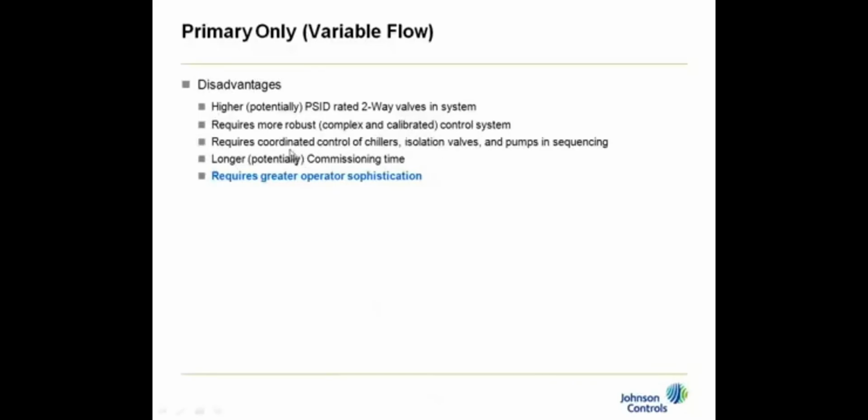Now, another disadvantage is that it requires a coordinated control of the chillers, isolation valves, pumps, which means that there needs to be a meeting during the design phase before everything is installed, with the consulting engineer, the chiller supplier, or at least the specified one, the pump supplier, the control supplier, and the valve supplier, to make sure everyone understands the sequence of operation that the consultant wants to use, and make sure everyone's limits are out there so that there isn't any problems with the system later. If that meeting is done ahead of time, then the potentially longer commissioning time goes away. Really, there's no difference in commissioning if you do that ahead of time. If you don't do it ahead of time, then of course the extra time during commissioning is doing it then. So you can have the meeting before, you can have it after. It's just better to do it before because it's less costly.